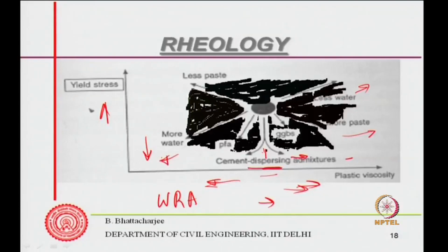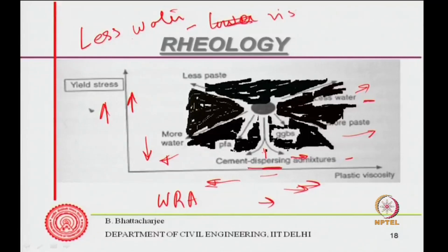Reducing water increases the viscosity and also increases tau 0, so the yield shear stress increases.